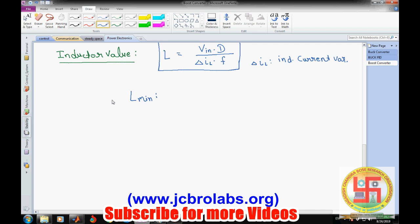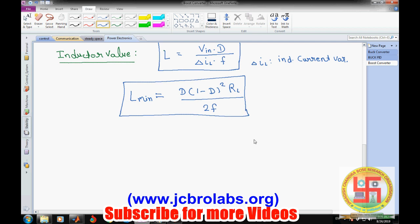The minimum value of the inductor for which this boost converter will remain in continuous mode is given by this formula: D into (1 minus D) square into load resistance divided by twice F. Similar to the buck converter, for the boost converter as well, the input output relation will not hold good for any value of R.